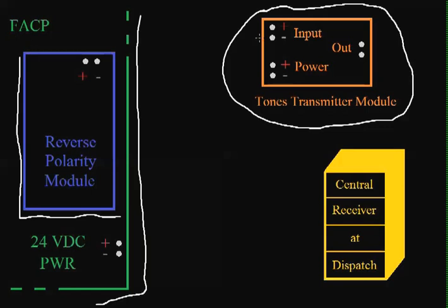But what this does is it takes that 24 volts, that reverse polarity signal, and it converts it to a tone. And that tone is kind of arbitrary for the user, for the technician, or for the dispatcher, but it's a tone that the central receiver, same thing we had in the last situation, which would receive that phone call from the digital dialer. That tone means something to this receiver. And this receiver, once again, would convert that to a signal that a dispatcher could understand.